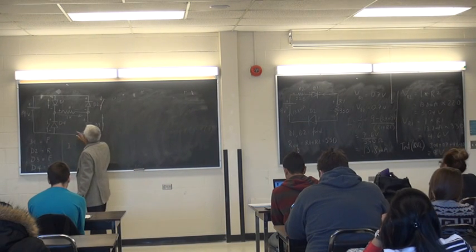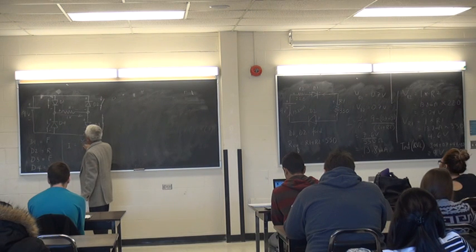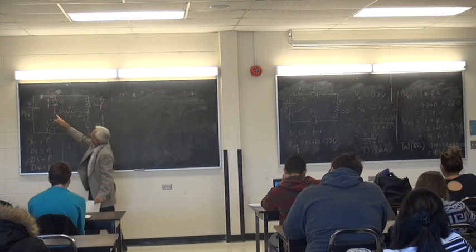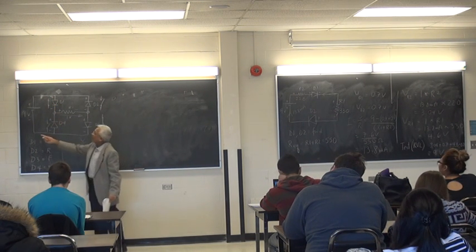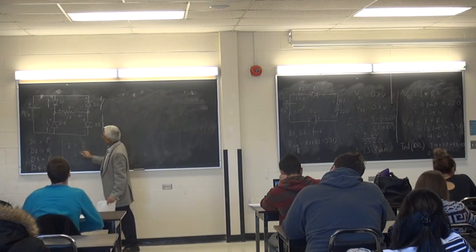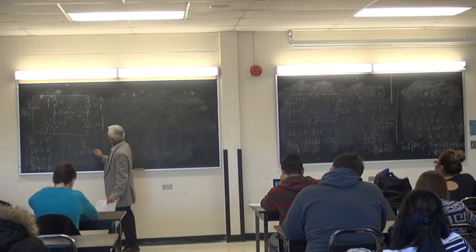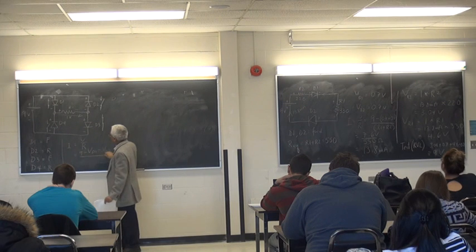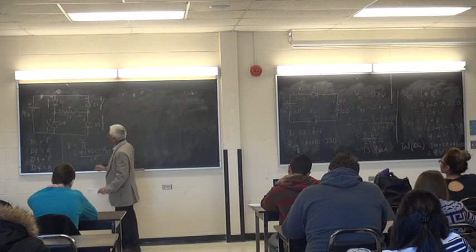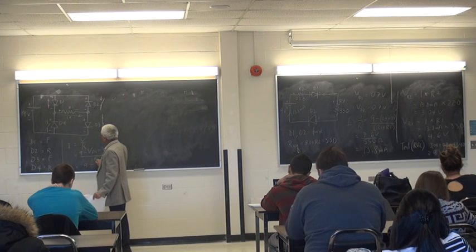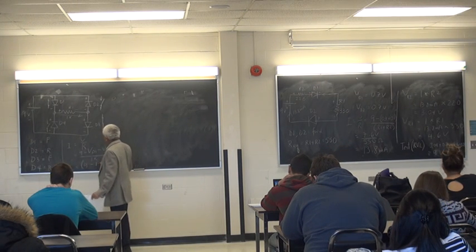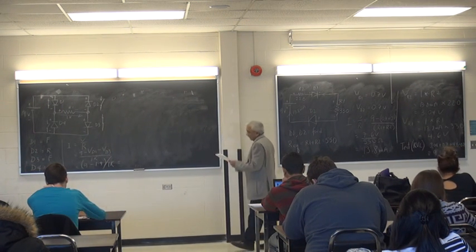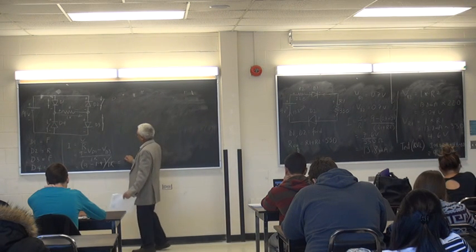So therefore, I at the resistor is V over R. What about the voltage? I've got a circuit with one diode, resistor, another diode, and back. So is it 9 minus voltage at D1 minus voltage at D3 divided by 1K? Everybody see that? 9 minus 1.4 divided by 1K? 7.6 milliamps.